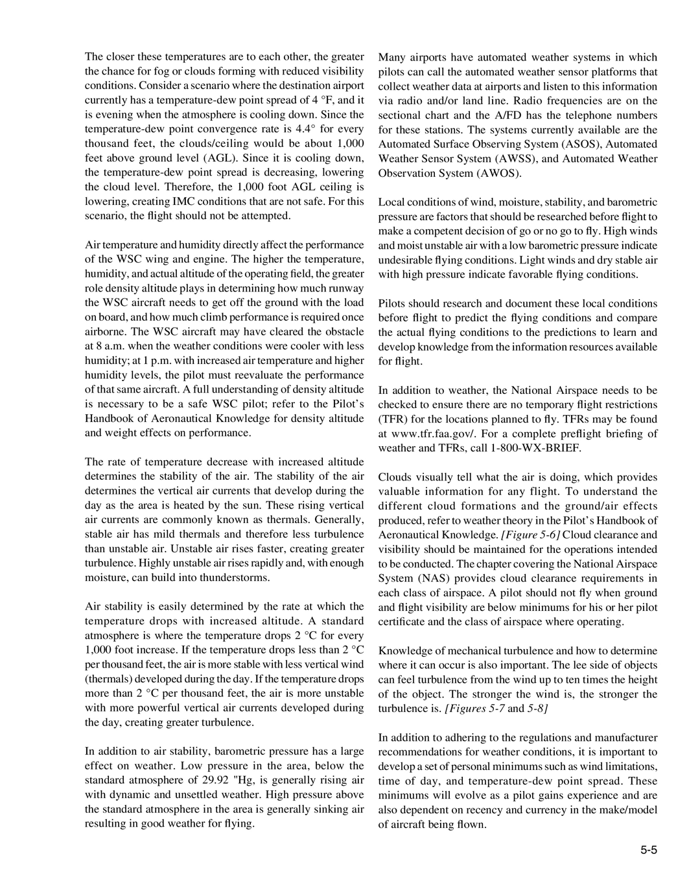High winds and moist, unstable air with a low barometric pressure indicate undesirable flying conditions. Light winds and dry, stable air with high pressure indicate favorable flying conditions. Pilots should research and document these local conditions before flight to predict the flying conditions and compare the actual flying conditions to the predictions to learn and develop knowledge from the information resources available for flight.